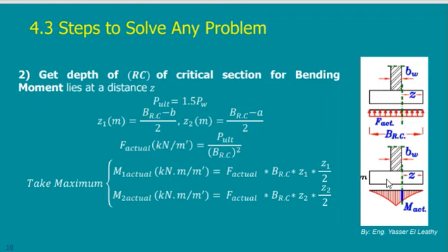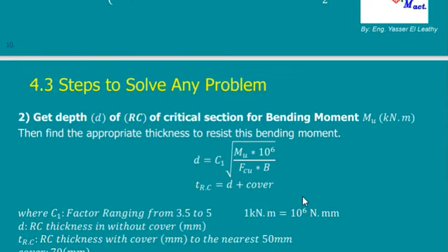The section is not just a rectangular section, it's a T section with a big column, so it's another thing. So I can use this reduced moment in my design. If you use the one inside, it's correct, but you are paying for nothing, so it's better to use this one. So now this is the moment, and I need now to calculate the depth.